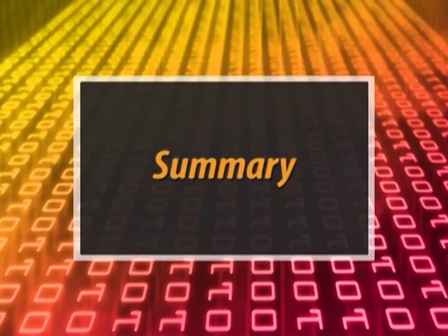In case of an inter-segment return, the top 4 bytes of the stack are popped. The first 2 bytes are assigned to IP and the next 2 bytes are assigned to the code segment. The stack pointer is incremented by 2 or 4 depending upon whether it is an intra or inter-segment return. An intra-segment jump needs a shorter address.